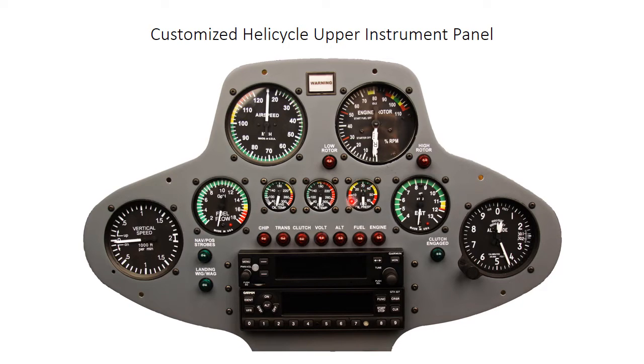This one here, engine oil pressure, I have a low and a high alarm, because too much pressure can also be an issue. We don't want to blow an oil seal out. Another one that you'll see in a minute is my voltmeter. I have a low and a high voltage alarm coming out of that guy. So those are some of the input sources.